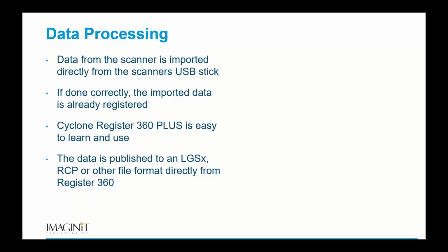Leica has phenomenal tools like detect moving objects that are going to go through and do a comparison of scans, and anything that moves between scans is going to be flagged. Once it flags that data, you can go in and say, yep, remove that, yep, remove that, yep, remove that. You have control. Or you can just say, you know what? I'm going to trust the software. Just remove everything that moved, because, you know, people standing in the way of the scans, etc.